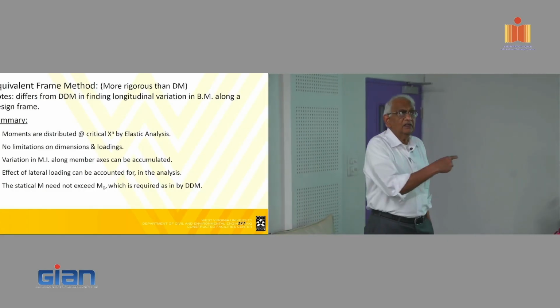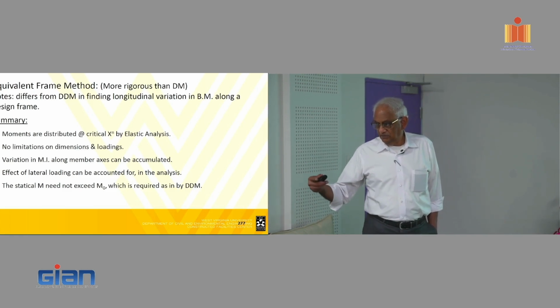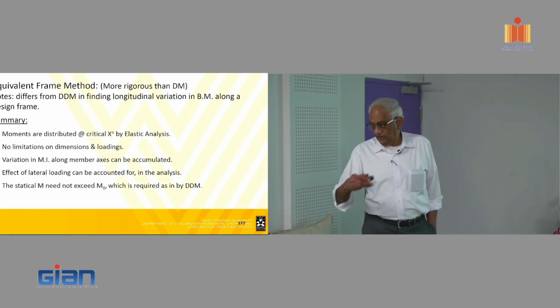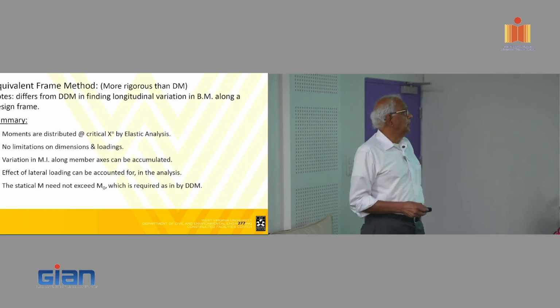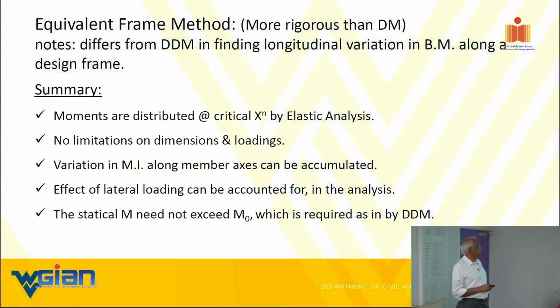The reason why it is allowed is because it is computer-based modeling. Moments are distributed at critical sections by the elastic analysis. There is no limitation on the dimensions and loadings. You remember we said in the DDM we have to have this, we have to have that: at least 3 spans, and spans cannot differ by more than 30%.